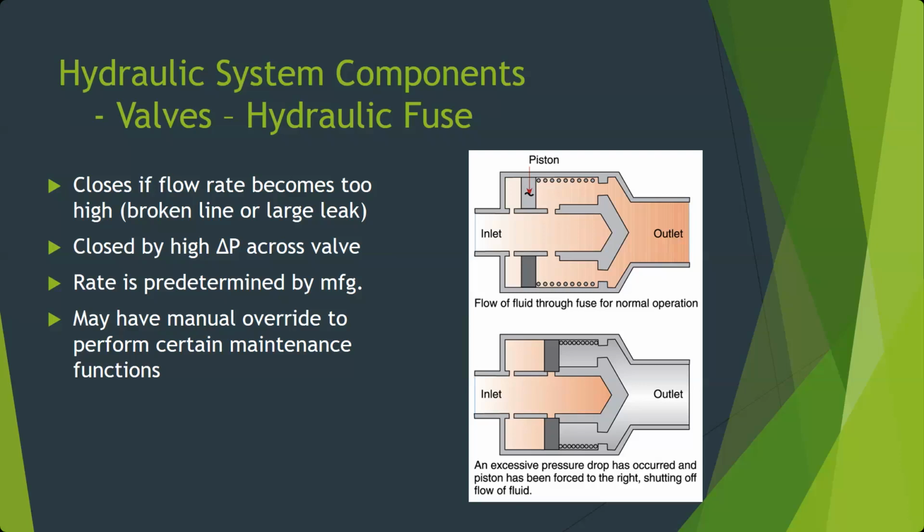At that point, the fluid on the left is going to force this piston to the right, and it's going to close off those ports to the outlet. And it will stay that way until you shut the hydraulic system off, and the pressure bleeds down to zero. Okay?